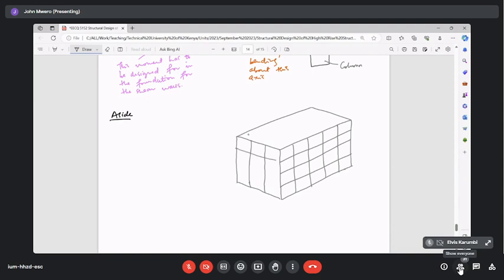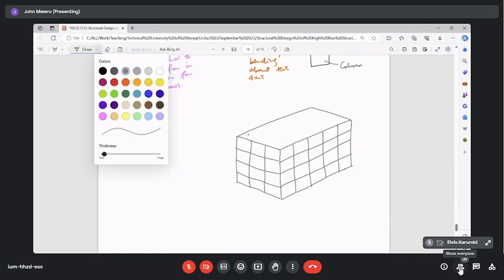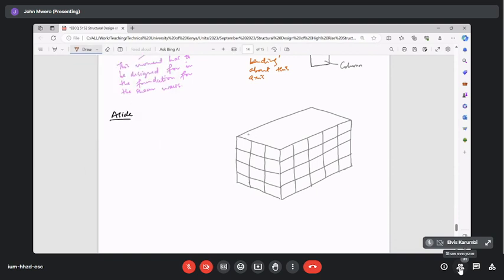So let's assume this is our building, the whole 18 floors of it. Once we calculate the wind loads, for example, per floor, we will come and load them per frame. We'll come and load those forces as point loads there in the X and in the Y direction, wind and earthquake. So we will have the building looking something like this with point loads at the nodes.